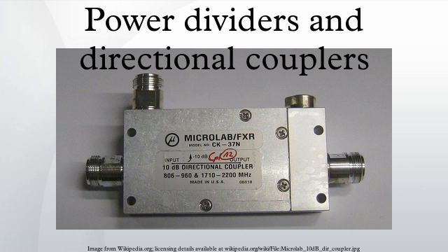In general, they are complex, frequency-dependent numbers. The zeros on the matrix main diagonal are a consequence of perfect matching. Power input to any port is not reflected back to that same port. The zeros on the matrix anti-diagonal are a consequence of perfect isolation between the input and isolated port.